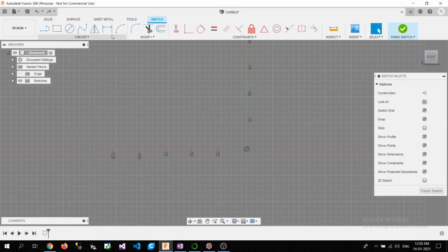But if you come to the fit point spline, we have to click on two locations, and then move it as we want the spline, and then click on the third location. So that is that. Now we can continue it as we want, but for each one, the basic minimum is two locations, say for example from here to here, and we are done. And then we need to select this axis and move it so that we can shape the spline.